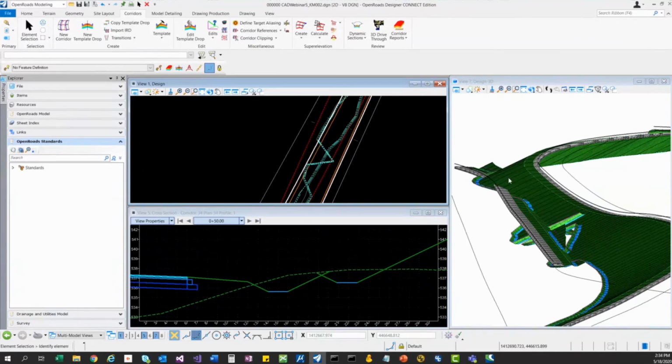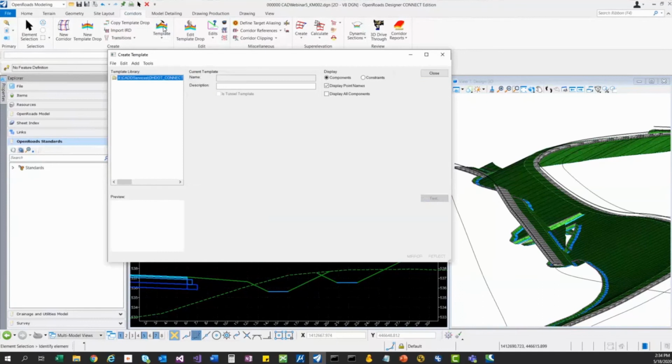All right, so for the wall, I need to have a constant slope come off of my higher elevation ramp here, and wherever that slope meets my wall is how high I want my wall to be. So as I go along this ramp, my wall height should be changing. Okay, so let's jump over, and before we do target aliasing, we're going to have to obviously update our end conditions to have a wall. So let me go over and do that now.